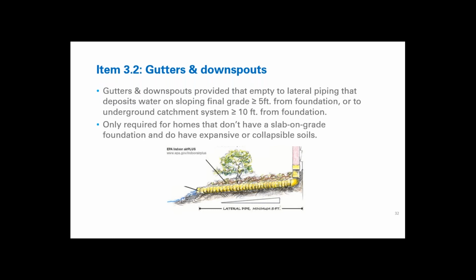They do need to be site specific because what you'll find with the regional maps is they'll give you a percentage, like the likelihood, and so it can give you some sense of whether this is going to be a problem or not. But you don't know until you test it at the particular site. So you do need an engineer to give you a site specific report there.